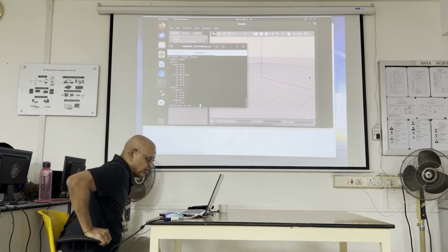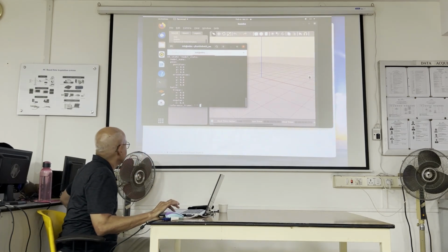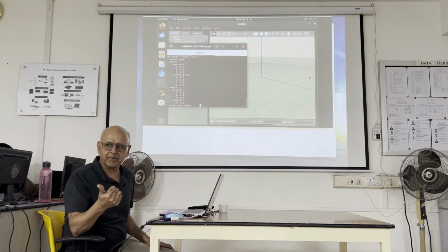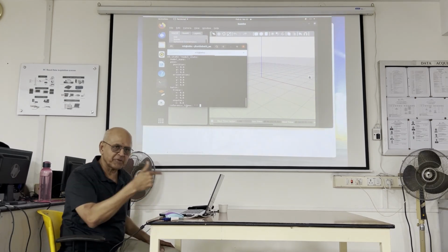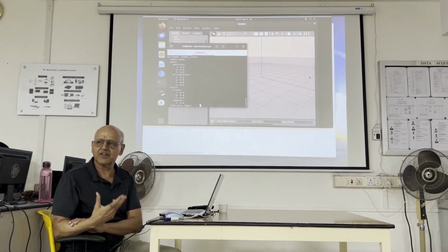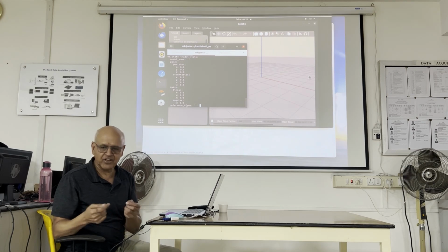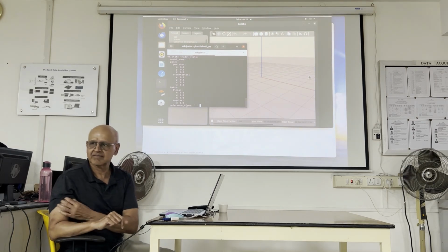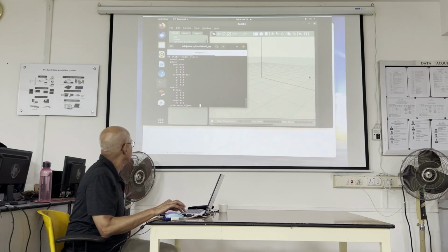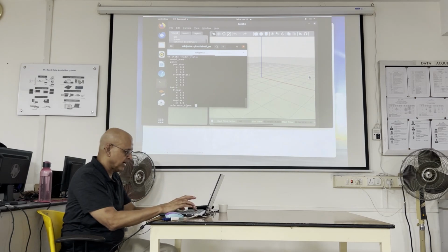So there are two things to complete. For instance here, see these codes here? You're supposed to fill in the reference frame. It's asking you, you want it to be moved, but with respect to which reference frame? Remember I told you there could be 17 reference frames? So it wants to know which reference frame you are talking about when you're giving it these coordinates. So you have to put world. I don't know whether tab complete works with this form entry, so I just typed it out.